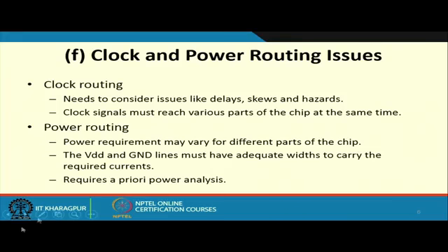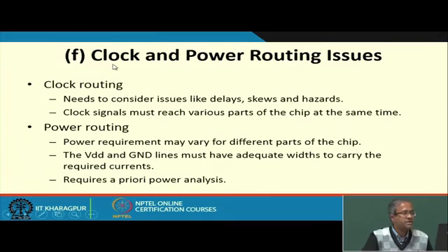This clock I have just mentioned earlier, this clock and power routing requires some special attention, because when you have the clock signals, it is not just the issue of just allowing the signal to be distributed to the different points where it should be. There are a lot of other clock related parameters that need to be satisfied for correct operation of the storage elements: rise time, fall time, setup time, hold time.